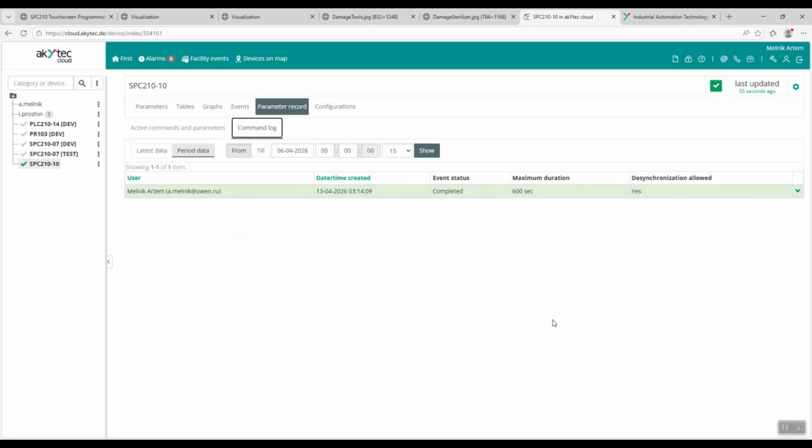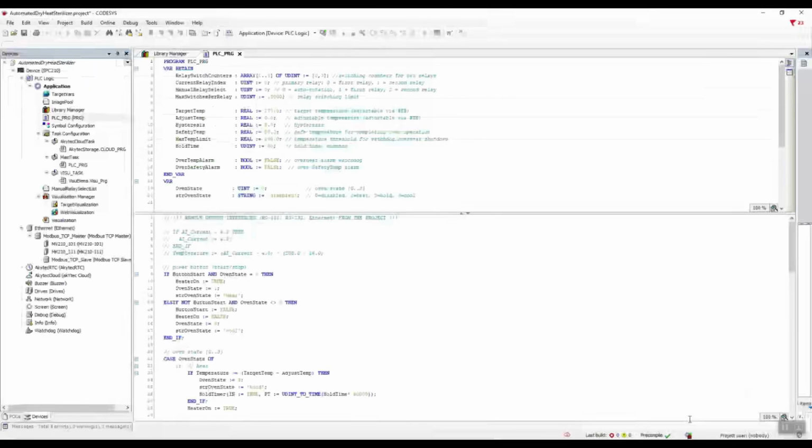And, obviously, we need to fix the flaw in our sterilizer algorithm. When manually pressing the main start button for the sterilizer, we also need to carefully check to see if this specific alarm is active. It is only in the case where this alarm remains false that we will then proceed with the next steps: switch the sterilizer to the heating state.